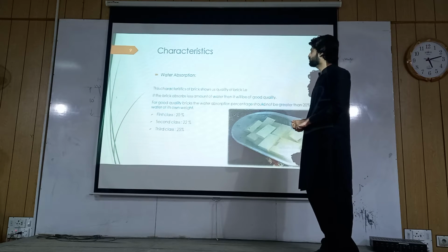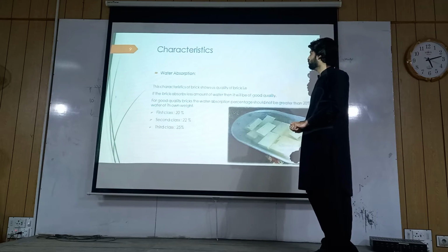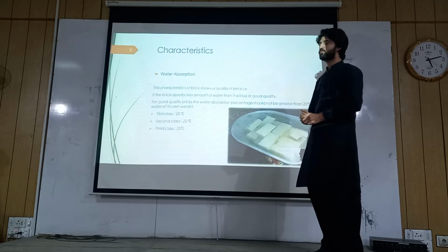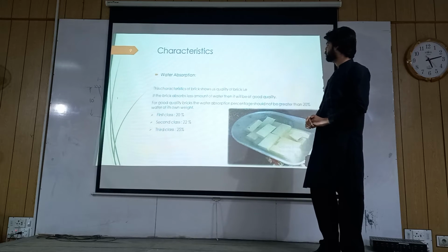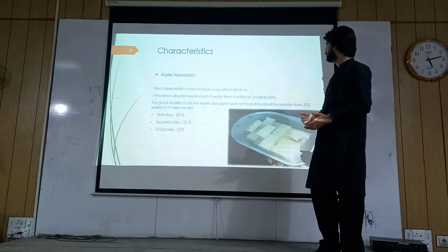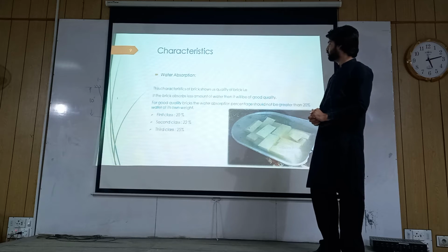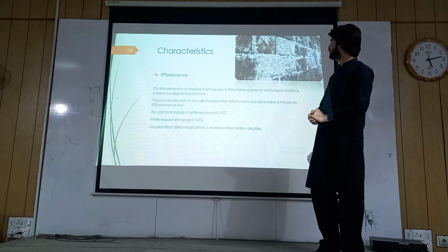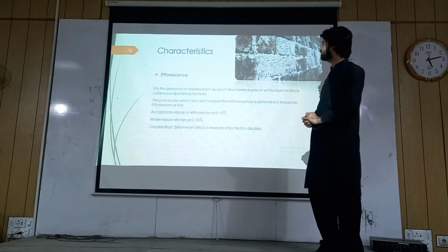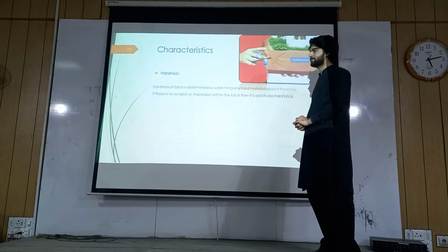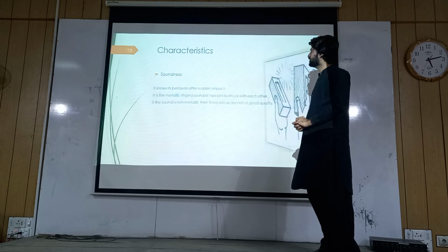Water absorption. This characteristic of brick shows the quality of bricks, like how much water it can absorb. The less water it absorbs, the better the quality it will be. For good quality bricks, the other characteristics are efflorescence, size, shape.